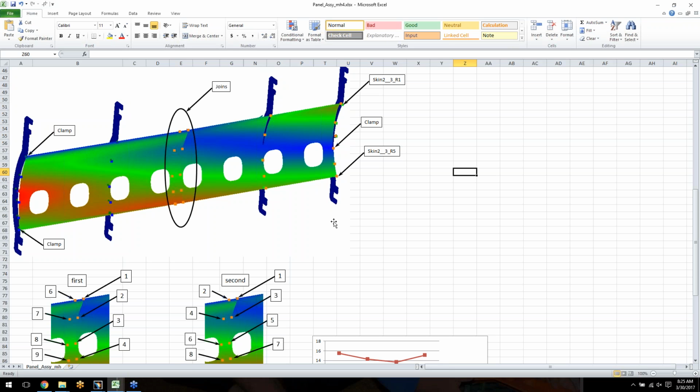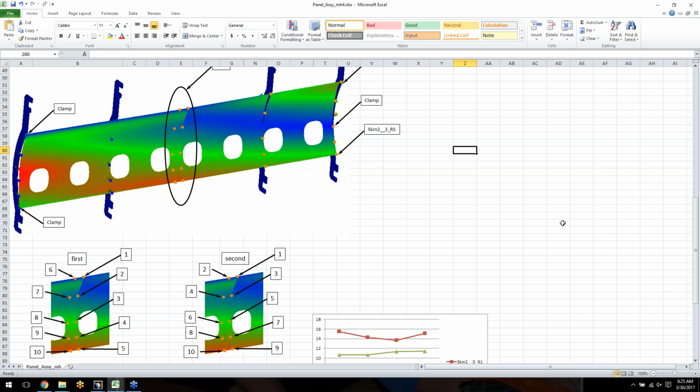So basically how the parts relax when you unclamp most of the points. Right. So you're considering how the welding and the joining affects them, as well as how they're going to relax after they're released from tooling. Yeah, so basically the clamping and unclamping, it's the same, but they will influence the numbers.